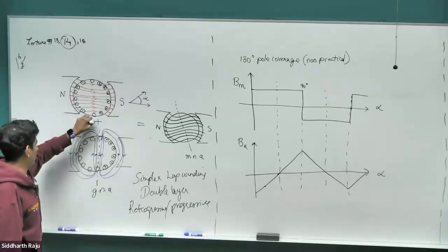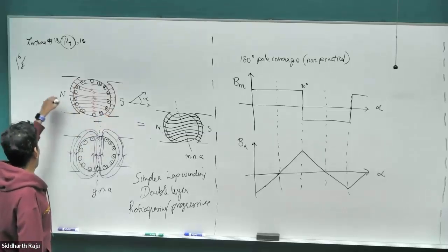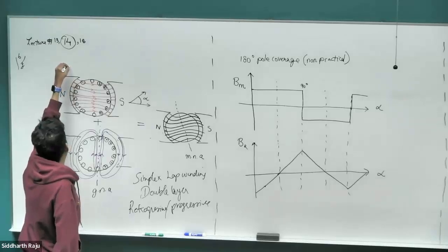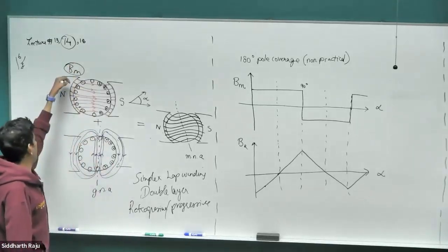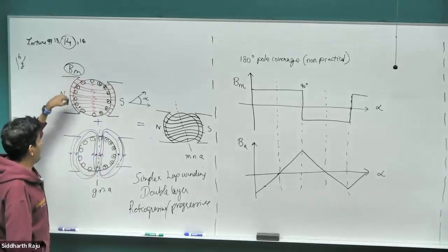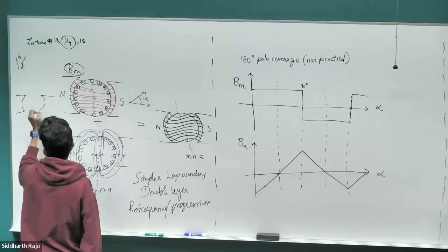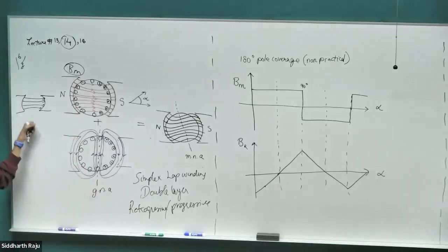So in the structure, we have the rotor, the armature, and then the north and south poles. We have the magnetic fields going from the north to the south pole, due to the magnetic field of the magnets alone. At every point, it's going to be perpendicular to the surface of the iron. Without the iron, if we just had an air gap there, these lines would have taken the shortest path. That would be the least reluctance pathway. The preference would have been going through the shortest path for the most part.